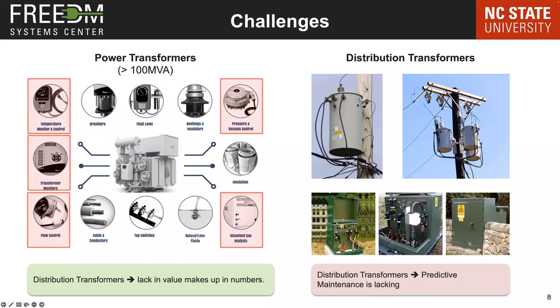But then you need special sensors and much smaller granularity to include all these factors in the transformer. Unless it's 500 kVA or some 50 kVA above, utilities are not really interested in being that conservative in analyzing all of these factors. If they just need an indicator to see if this is significantly overloaded, they'll go and make a replacement. But right now the practice is not to look at all the factors that affect distribution transformers.